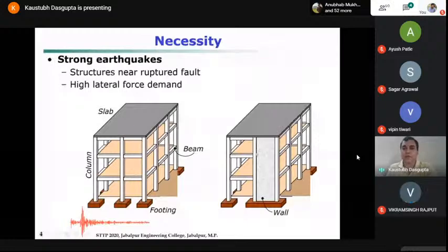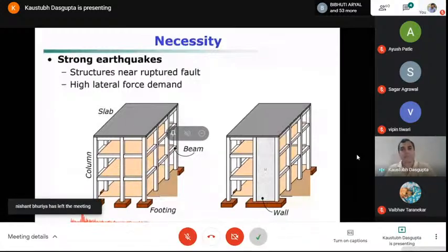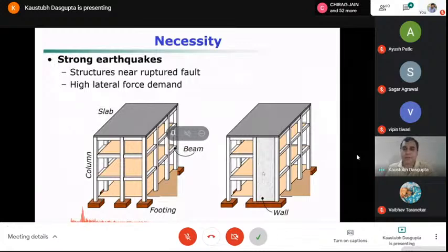Okay, so how do you construct this? Starting from the footing, when you are constructing the columns, you make the formwork in such a way that together with these columns, the intermediate concrete part is also constructed. This element has a small thickness in cross section, however the length is large. So it is like a planar element, something like a slab in vertical orientation. These elements are called walls, structural walls or shear walls, right?